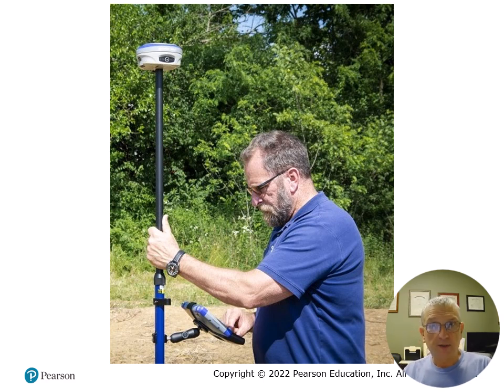And it's usually that a driver goes past a barrier or swerves off the road or something. You have to be mindful of your surroundings and have situational awareness when you're surveying. Wear high visibility vests. And if you're going to be around a road, it's good to not be doing solo surveys around a busy road so that one person can help watch for you. And that's an absolute requirement with railroad surveys, actually, even though you can hear a train coming a lot easier than you can a car.